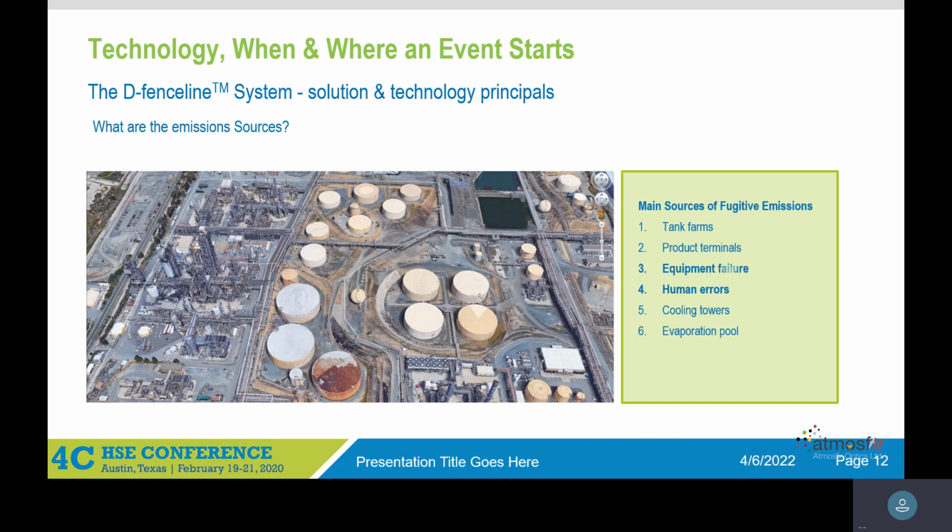So we talked about where the emission is coming from. Because we're measuring the source, we have FTIR at the chimneys, the source, we have GCs at the source, and we can control the source quite often. If there is a leak going out of a duct, we will sense it. But we will not sense if someone didn't connect a connector properly, didn't close the valve properly, or if you've got a fugitive emission.